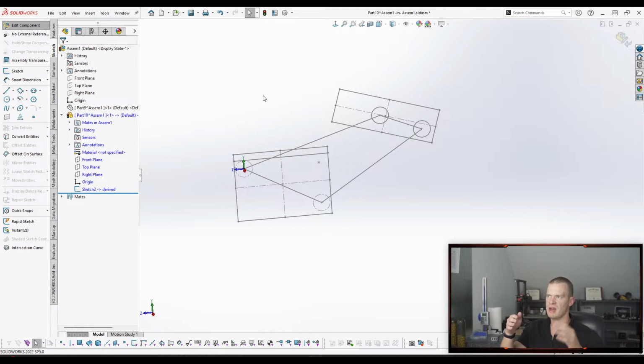If we copy that same sketch into those 4 different parts, we're now passing information amongst those 4 parts at the same time. So if I go and change this linkage length, all 4 parts will update in turn. And so that's top-down modeling, right? I make a change at one location, and that information is pushed down the tree into the other parts, and everything else updates.